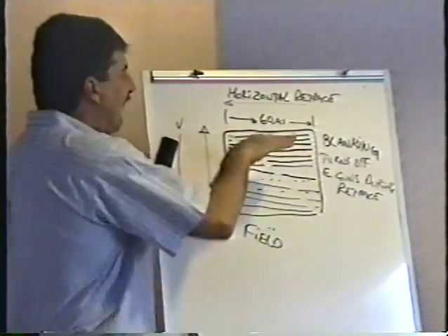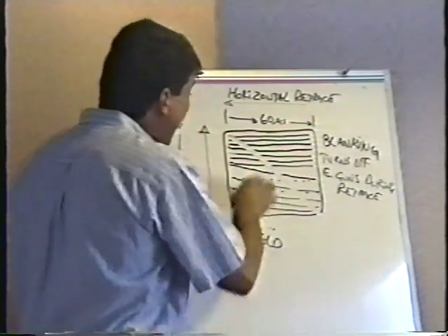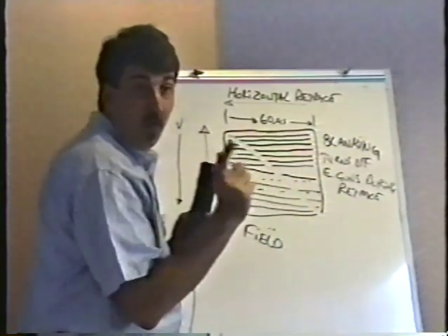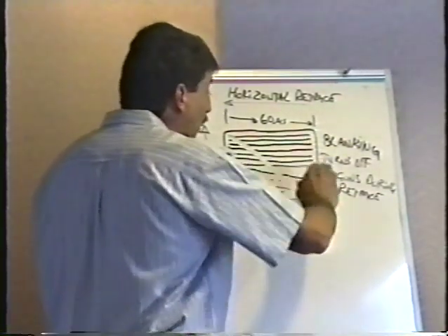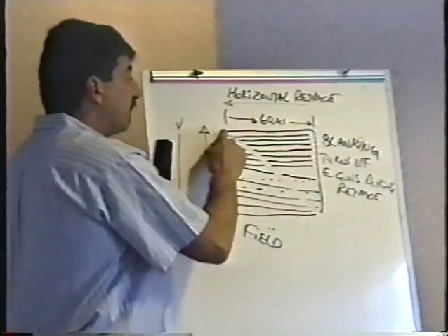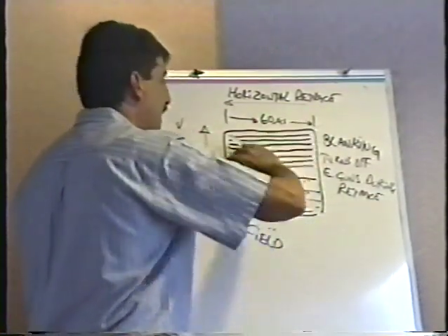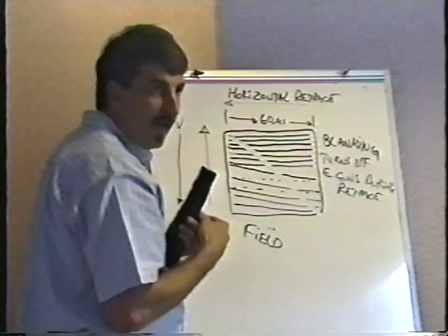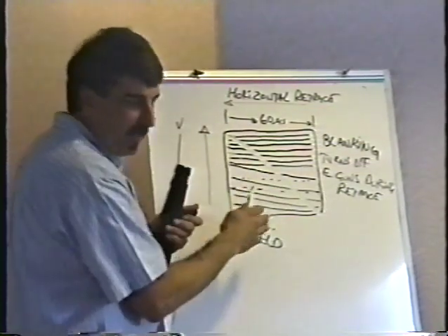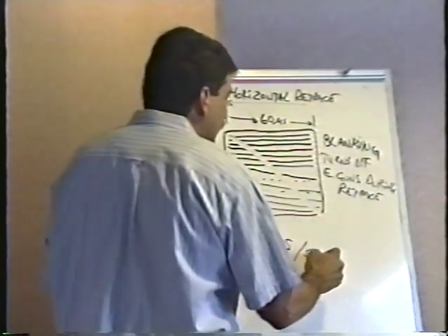All right. Until finally the whole screen is filled with these lines, these raster lines, and that's called a field. Then the beam comes back to the upper left-hand corner, and before this has a chance to fade out, it does the same thing all over again. It comes back up to the top, draws each line again in the same place, and does this over and over again. It does this 60 times a second. The monitor paints 60 fields per second.